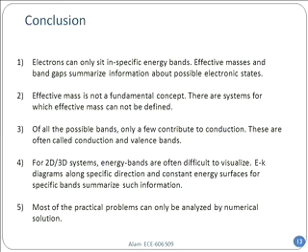Effective mass, I said, is not a fundamental concept, and there may be systems where the effective mass cannot be defined properly. Do you remember the graphene relationship? You should also convince yourself how to think about carrier transport in those cases, and how to think about the negative effective mass or zero effective mass in those cases. The third point was that only a few bands contribute: the conduction and valence band, partially empty or partially full.